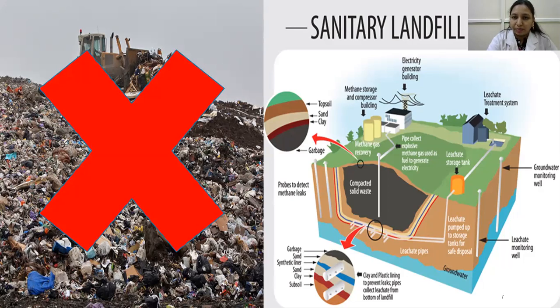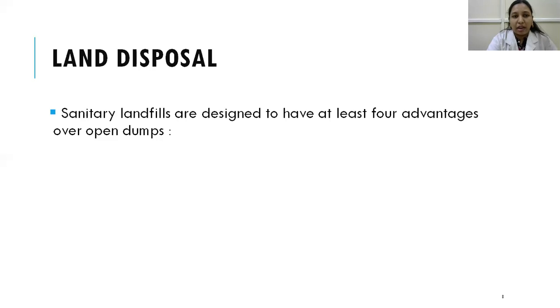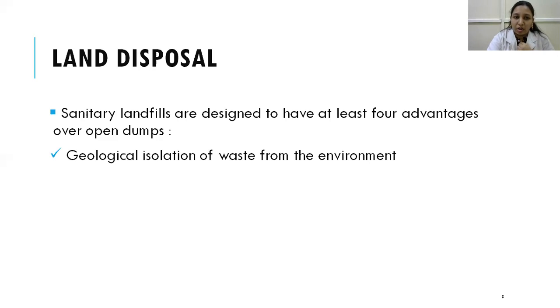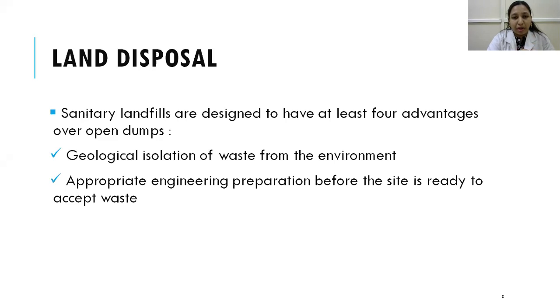So this is a very good method which is environmentally sound for the disposal of healthcare waste. Sanitary landfills have about 4 advantages when compared to open dumps. There is geological isolation of waste from the environment. As we have seen, there is a clear-cut space between the groundwater and the waste, and appropriate engineering preparation before the site is ready to accept the waste.